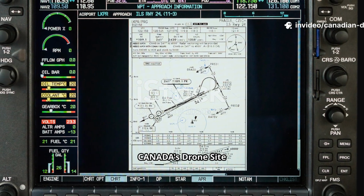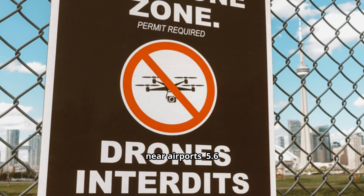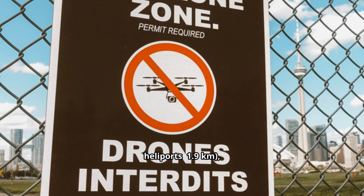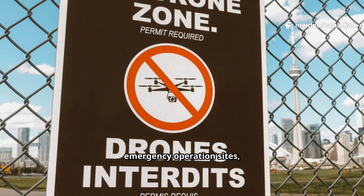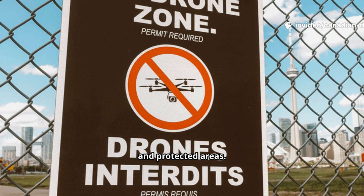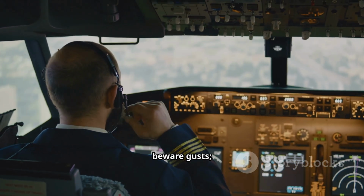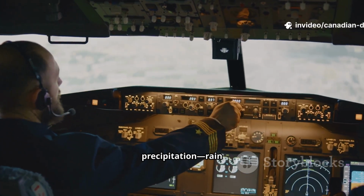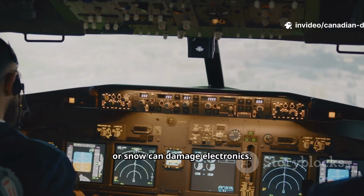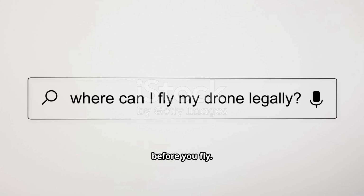Always check NAV Canada's drone site selection tool on the day of your flight. Avoid no-fly zones near airports, 5.6 kilometers radius, heliports, 1.9 kilometers, plus national parks, military bases, emergency operation sites, and protected areas. Assess conditions. Know your drone's max wind rating and beware gusts. Maintain VLOS and watch cloud ceiling and visibility. Avoid precipitation. Rain or snow can damage electronics. Check NOTAMs for temporary flight restrictions such as air shows, VIP movement, or rocket launches before you fly.